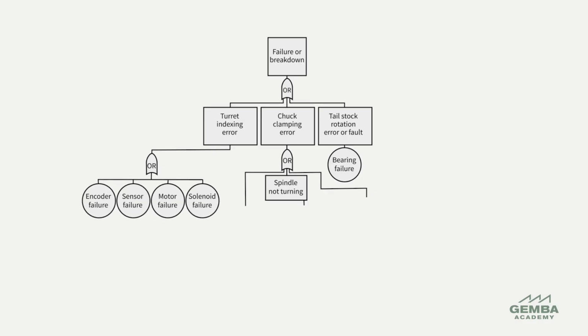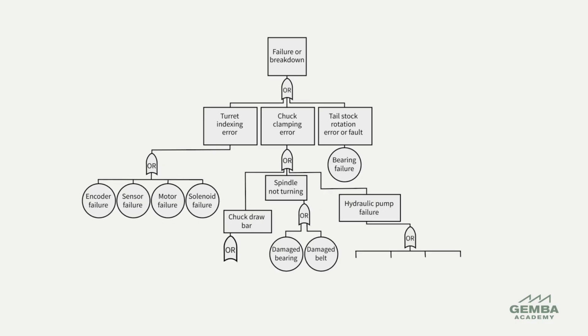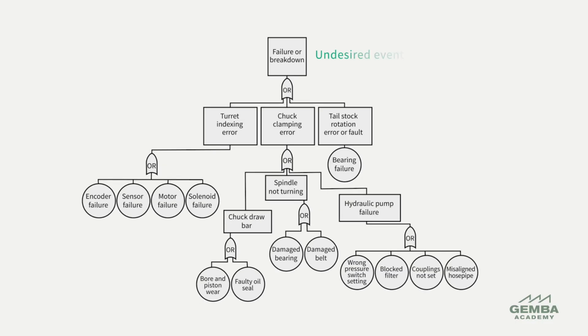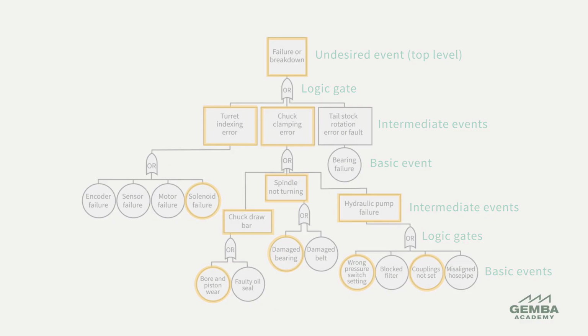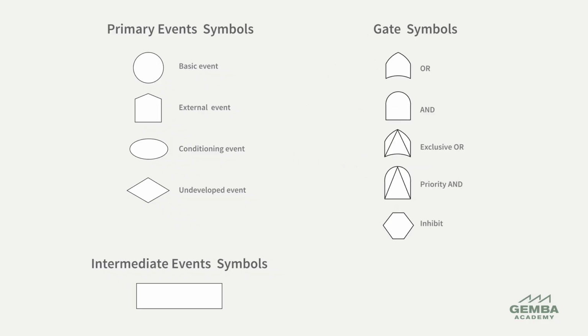The fault tree is a visual model of the logical relationship of the unwanted event to more basic events that contribute to it. We use the fault tree analysis to methodically investigate what happens to a system when there is a change to the status of one or more elements of that system. We want to know how likely it is for a specific combination of these changes to result in an accident, defect, or breakdown. Fault trees are structured with symbols for events, gates, and transfers.